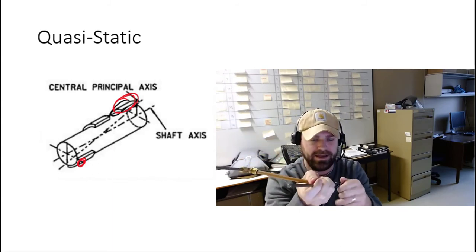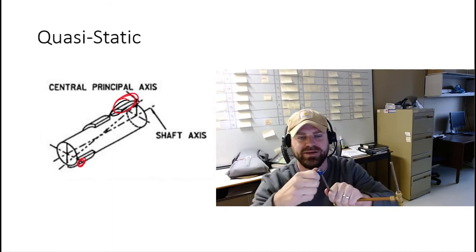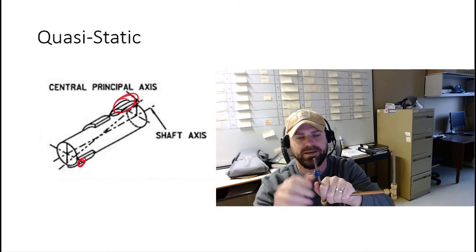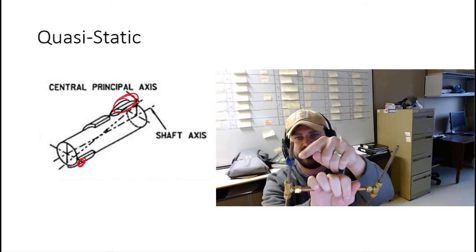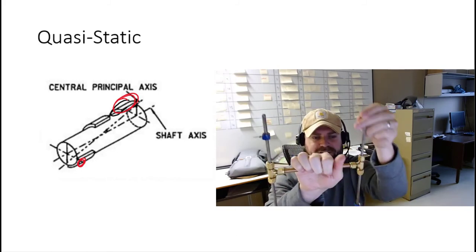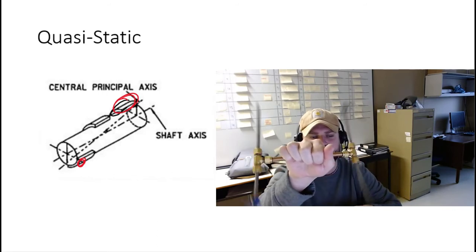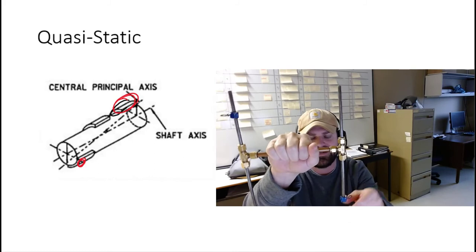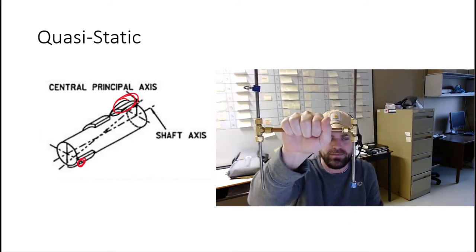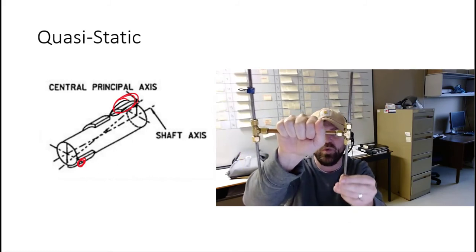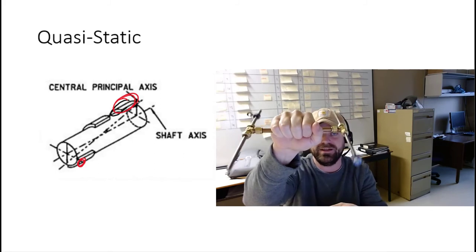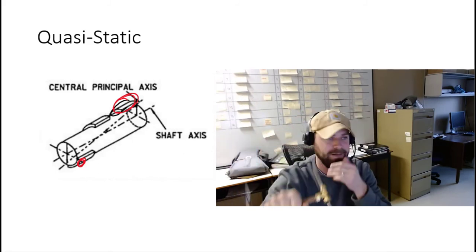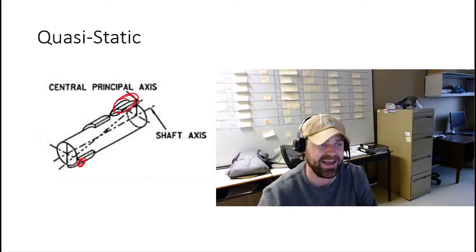Okay, and here I can adjust it by doing this. I've moved this weight a little bit closer to center. So when I spin it, I still get the wobble, and it's detectable at rest because there's more weight further distributed out that it wants to find that position. So it's a combination of static and couple.